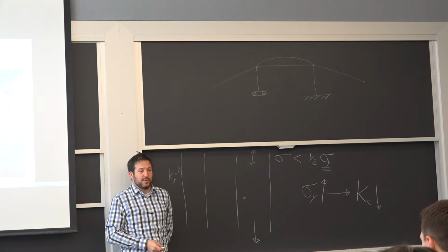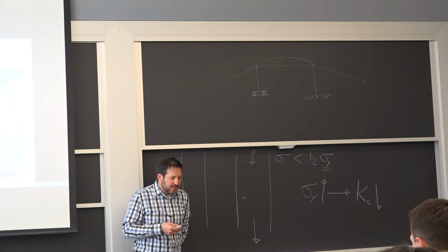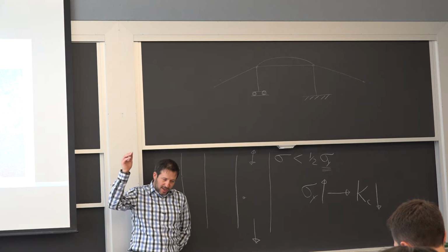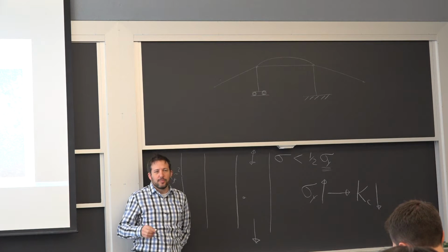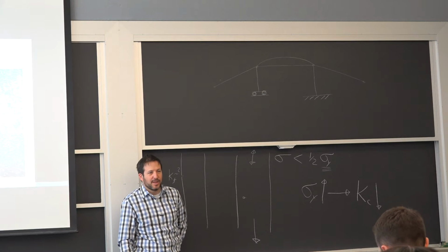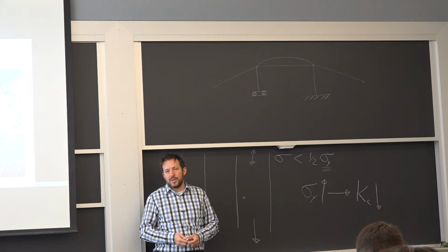and now it's only 25%. So it's how I want you to start thinking when you have cyclic loads, or if you have sustained load with plastics, your capacity is always going down significantly. We're not talking 20%. It's a factor of 2, a factor of 4, a factor of 10 sometimes with plastics between the short-term burst resistance and the long-term capacity.